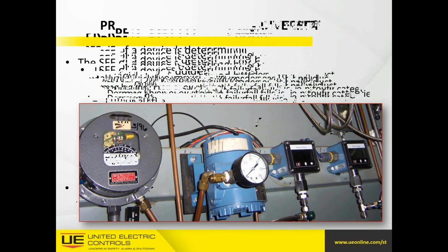But once the manufacturer boiled it down and found where their problem was, it was a lack of diversity within their electronics. To save some money, they created 3 levels of electronics that were common mode, as opposed to prior to that, when they had 2 levels with some diversity in their electronics. So during manufacturing, if one mode of this gas pedal failed, the other 2, which were put in there for redundancy, would also fail. It was called common mode failure in electronics.